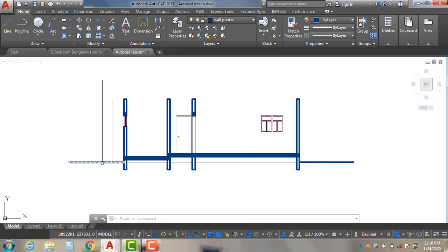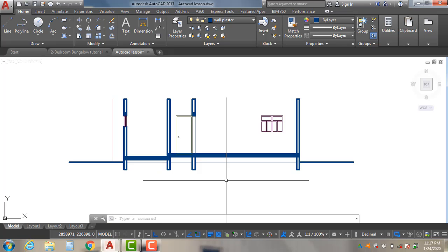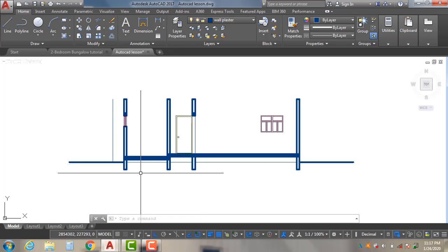Now these two thick lines show the natural ground level. So we want to show what happens at this natural ground level. From this first one, this infill that we did here is called the 150 mm oversite concrete slab. After that, you have your 300 mm hardcore. That's the hardcore that you are going to place before you have your well-rammed earth filling. By the time you enter into construction, you understand all these things.